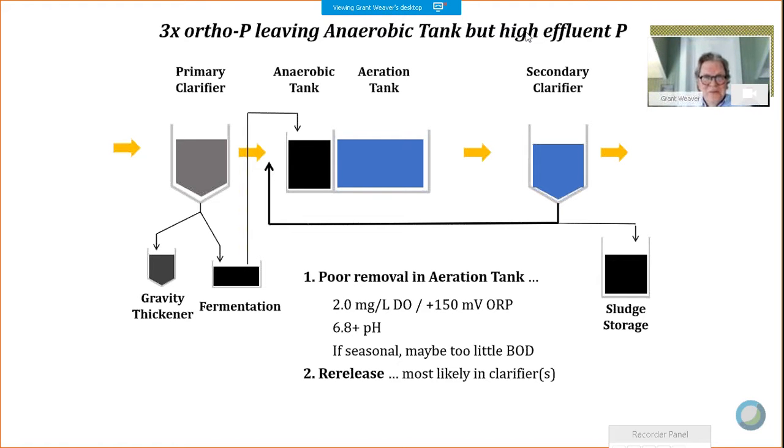Just the opposite of the cases where I do want it for solids. Now I don't want any solids settling once I've got this aeration tank and I've got my soluble concentration really low. And I don't want any solids anywhere settling out and dying, decaying, and releasing phosphorus into the solution. So how do you monitor that?